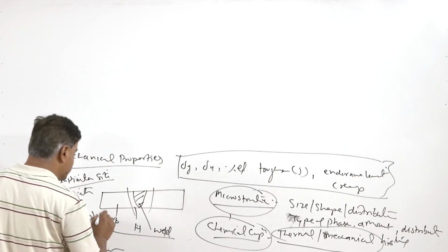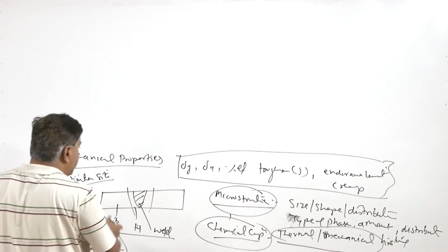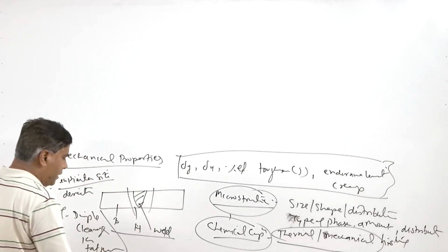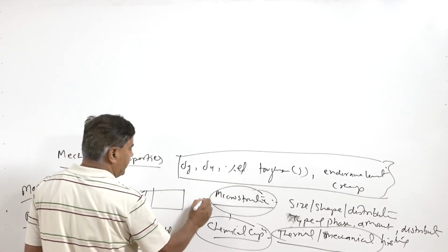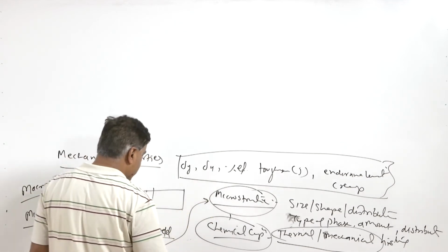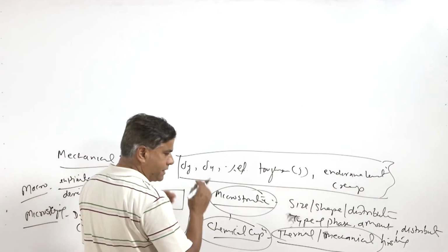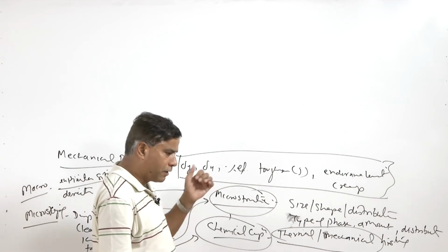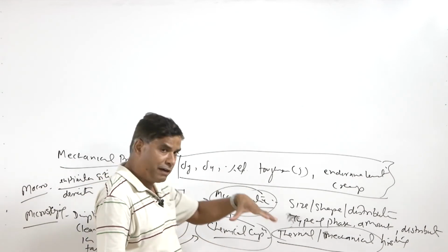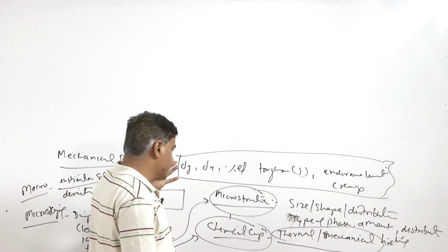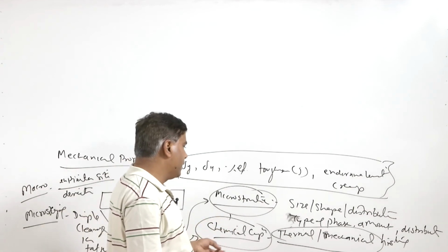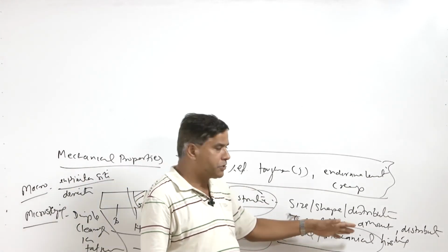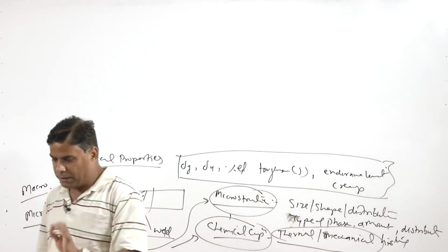As per the case, these will indicate the kind of loading conditions and the mode of fracture which has been involved, and metallography will help us to establish the microstructural aspects. Chemical analysis will help to establish whether the chemical composition of the base metal, of the heat affected base metal, or of the weld metal was as per the specifications or not, and if for the given composition everything is fine, but the thermal and mechanical history of the product was not as per expectation.